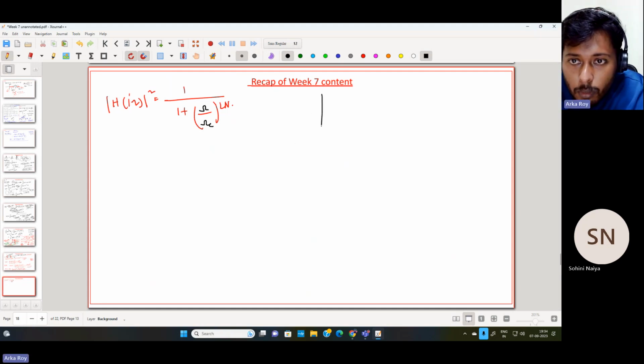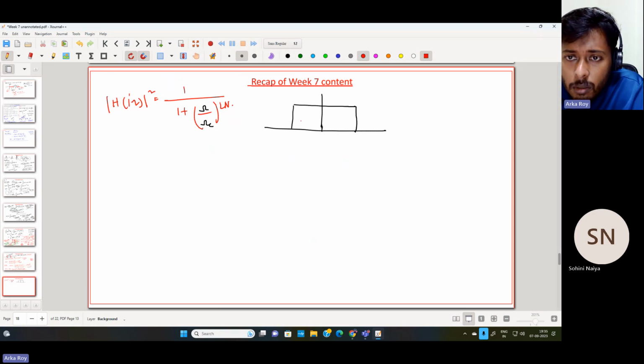So if I try to take an analogy with this brick wall characteristics, this is the standard brick wall characteristics that I am very happy to achieve. But because of the continuity constraint, I cannot get this kind of brick wall characteristics. Instead of that, I will try to maintain some similar properties in the passband, and here I will see that there will be some attenuation effects.